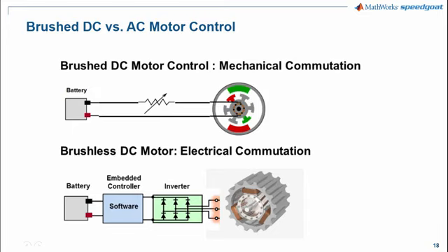The brushless motor is more efficient as it doesn't have these lossy, messy mechanical brushes, but the trade-off is that the commutation must now be done by electronic commutation. This is typically through the use of a microcontroller running some sort of feedback loop algorithm.